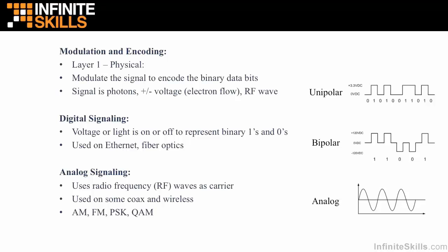And what I can do, if I want to encode a binary 1, I can make that wave taller. In other words, I'll use greater voltage, greater power for that one part of the cycle to encode a binary 1, for example. And if I want to encode a binary 0, I will decrease the voltage below the carrier signal that we see there. So a lower power will represent 0 as the encoded signal. And I'll modulate the voltage or the power of this first portion of the sine wave, either higher or lower, to encode a binary 1 or 0.